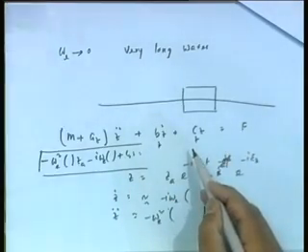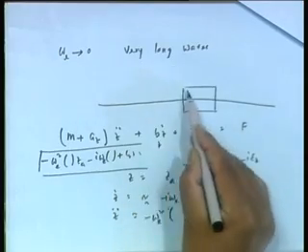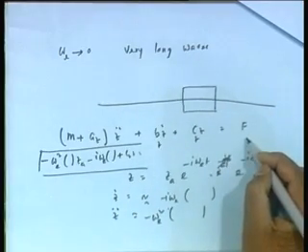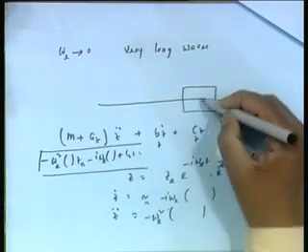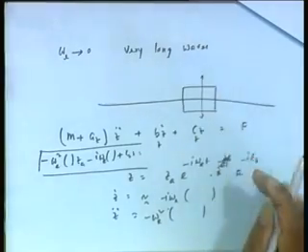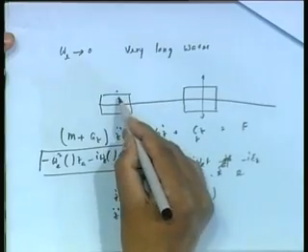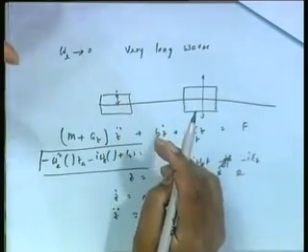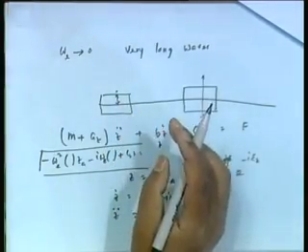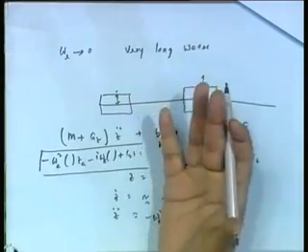Now what is cz? We will come to that, but what it means is that it is happening so slowly, in fact we will find that the phase gap becomes 0 with respect to the exciting force. This will simply go up and down with the water, means if water goes up, body goes up, water comes down, body comes down. It will simply ride the wave by hydrostatic force. So that means every time if you stand here, you are going to find your water surface or freeboard the same, the freeboard is going to remain the same. You don't even feel that you are moving, because first of all it is moving very fast. So that is what has happened in a tsunami type of wave, very long wave.